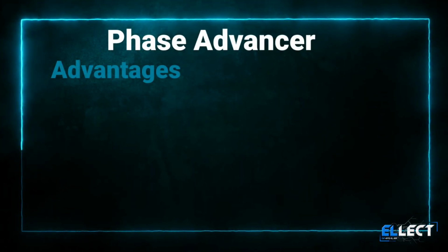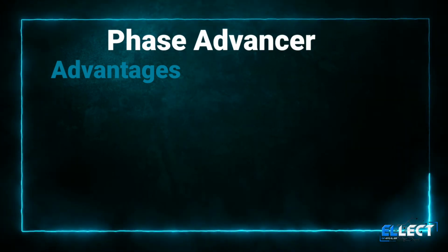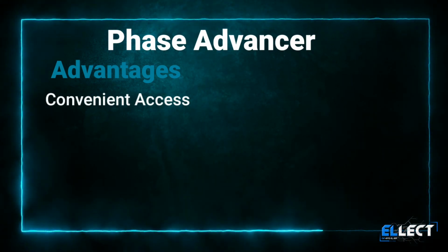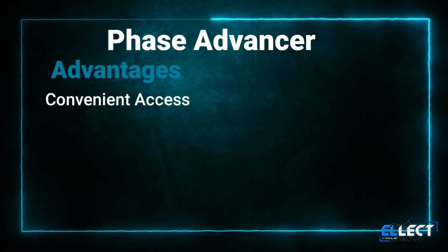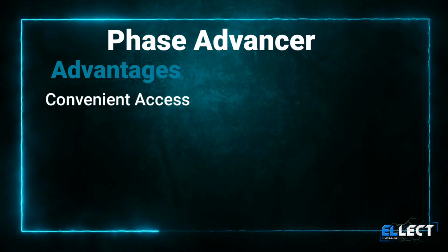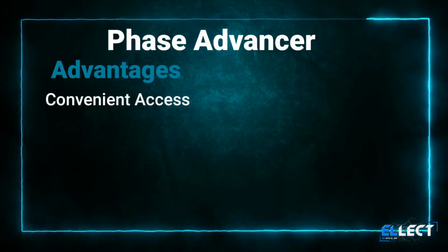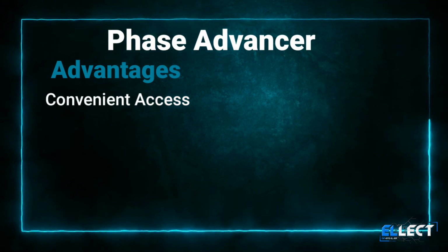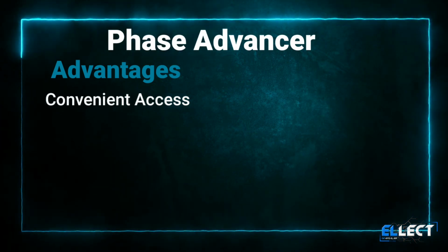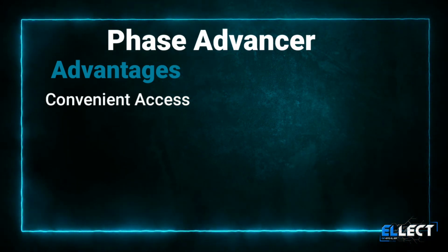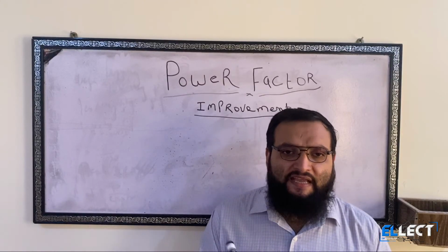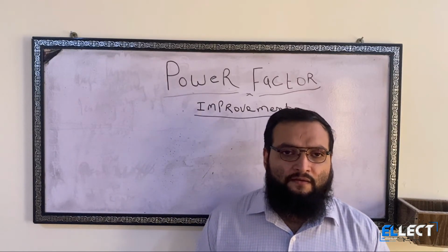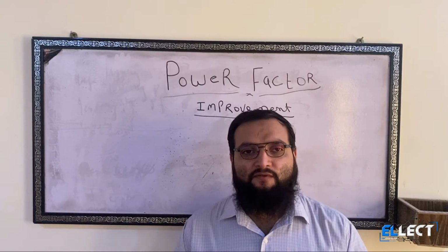Now the very first advantage: it can be used in places where a synchronous motor is unacceptable. There are many places where a synchronous motor cannot be installed due to noise, because those places are very sensitive, and the lagging kVAR component of power or reactive power drawn by the induction motor may be reduced by using external AC exciters which can be supplied at the supply frequency.